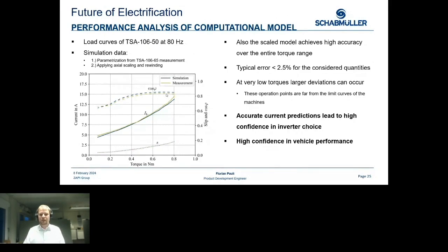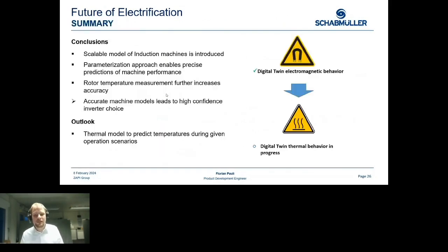So to sum everything up, I've introduced the scalable model of induction machines, and we are using a parametrization approach which enables precise prediction of the machine performance. If we take temperatures, especially the rotor temperature, into account, we can further increase the accuracy of our models. And as mentioned before, accurate models lead to a high confidence inverter choice.